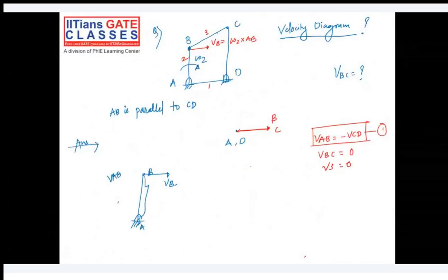So there is basically no relative velocity between them, so that is why we are getting 0 answer. Omega is actually 0 between B and C. At whatever omega B is rotating, C is also rotating at the same omega. That is the main thing here to understand.